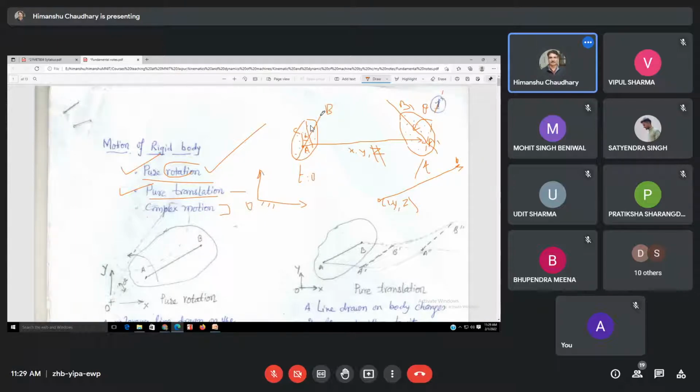From my initial position AB, now this point C comes here, and this is now C1. This is alpha from A1B1 to A1C1, because the distances A1C1 and B1C1 will not change. The only change is the angle theta. So the position of C1 is determined by angle theta plus alpha. So you can find the position of all points by knowing angle theta and displacement x and y.